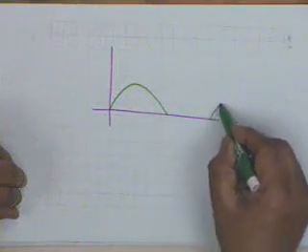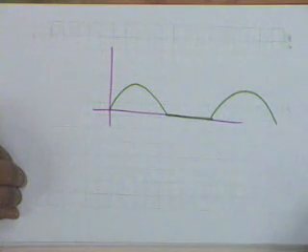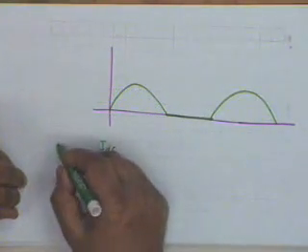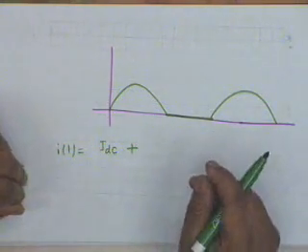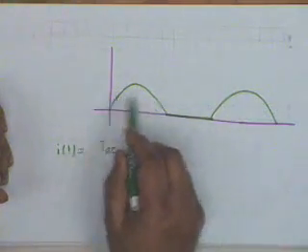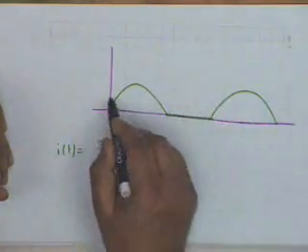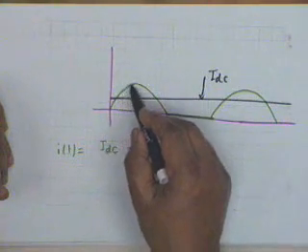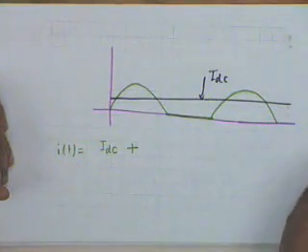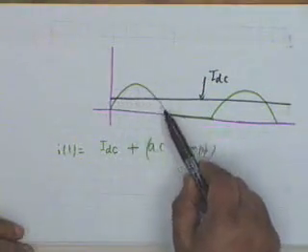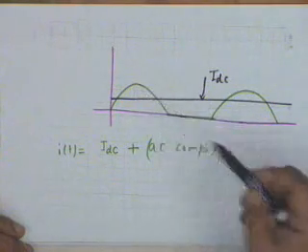My waveform of the current is like this, the green curve. This, as I said, can be written as an average component IDC plus a component which can go positive as well as negative. If I take out the average value from here, suppose this is my IDC level, then obviously the current will be positive here, the AC component. I have not written this. AC component represents the green curve minus the black curve, and therefore it can go positive as well as negative.